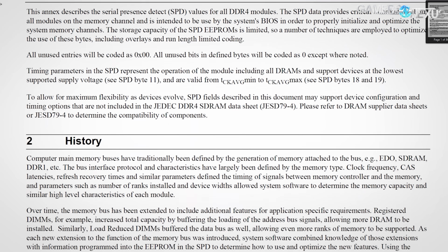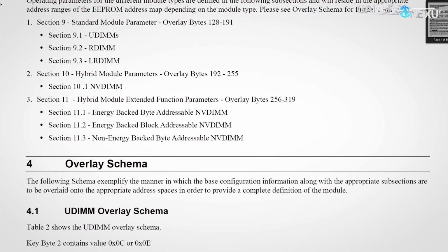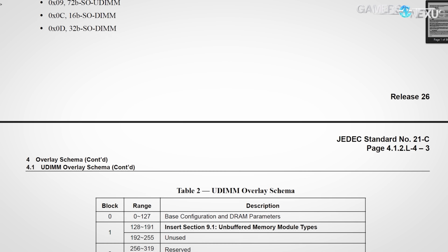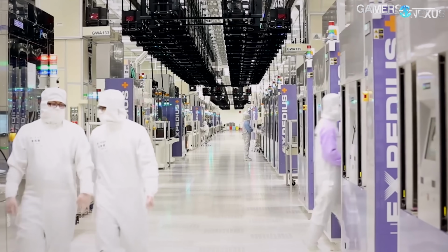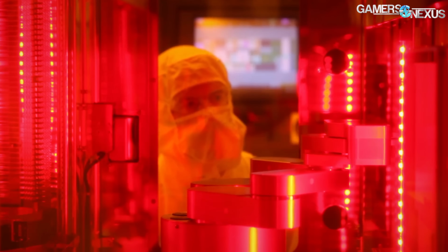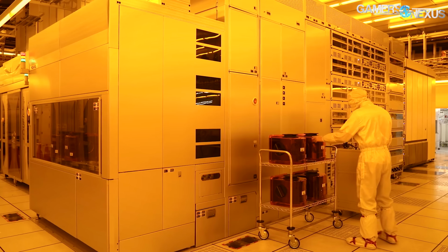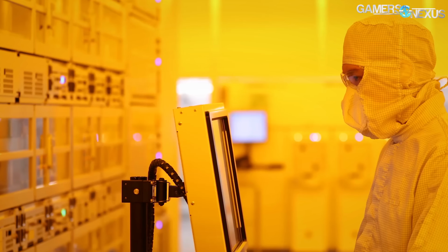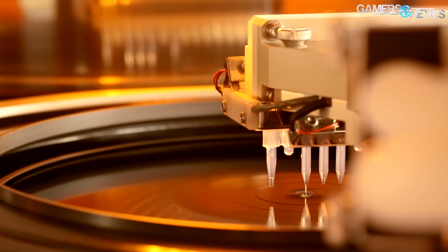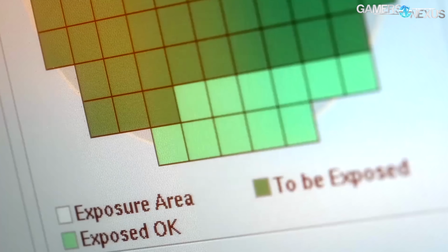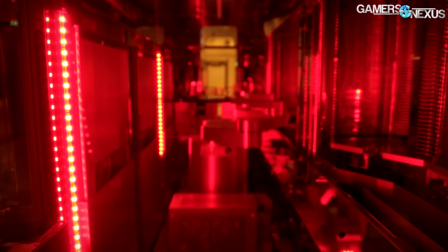The JEDEC, or Joint Electronic Device Engineering Council and Solid State Technology Association, is an organization that publishes standards for DDR4, DDR5, SSDs, mobile memory, ESD, GDDR6, and more. They're responsible for standardizing and defining everything in our article and this video, from abbreviations to the entire concept of DDR4. As part of this, JEDEC publishes tables with baseline timings for different RAM types, several of which are saved in SPD. Memory manufacturers produce strictly JEDEC-defined varieties of RAM, like DDR3 1600 MHz, 11-11-11-28, but can make them capable of higher speeds and market them as such.